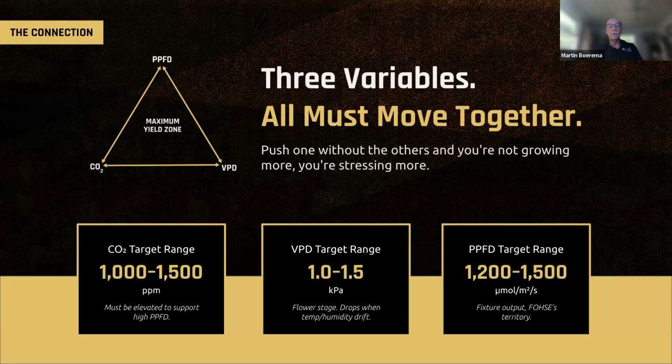And as we go through the growth phases, you go from veg stage, a VPD target of about 1 kPa, where you promote vegetative growth and broad leaves, creating that great foundation for flower growth, to 1.5 kPa in flowering stage, where you promote moderate stress, still strong growth, still strong photosynthesis, but with added stress,